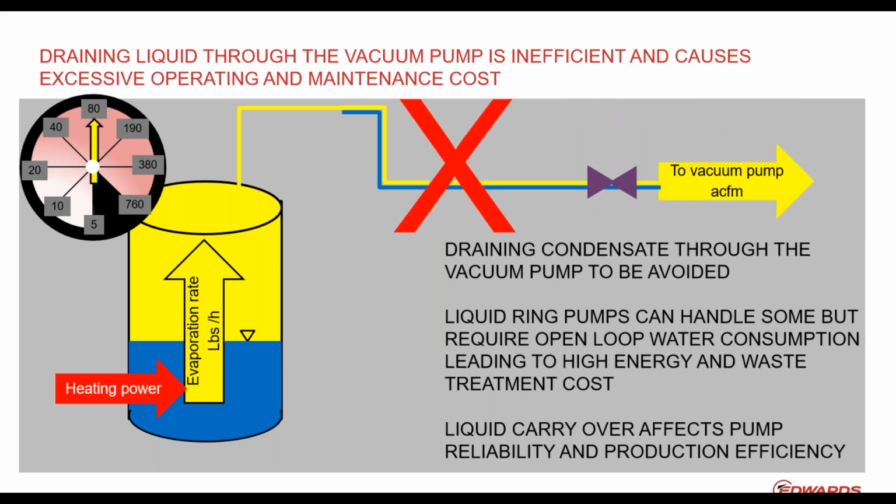So before we close this webinar, just briefly, I mentioned it earlier, it is not very good practice to plan and have or allow for a liquid drain flow into your vacuum pump. I know that liquid drain pumps, for instance, can handle some of it, but it is not very good practice because you can just knock it out.